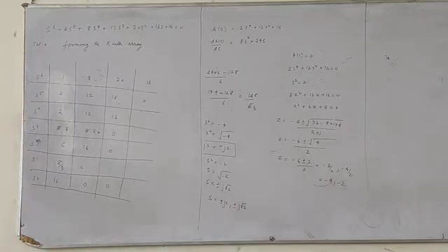Hence the system under investigation is, what is that? Marginally stable. Everything is on the imaginary axis. Hence the system under investigation is a marginally stable system. You have to remember when the system will be marginally stable. You cannot ascertain it from the table, you have to ascertain it from the roots. Because rho is becoming prematurely 0, the assertion has to be done from the roots.